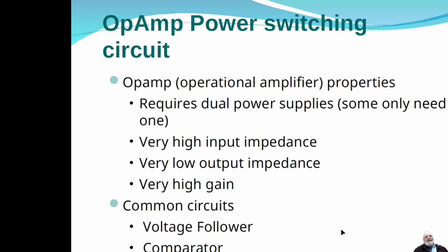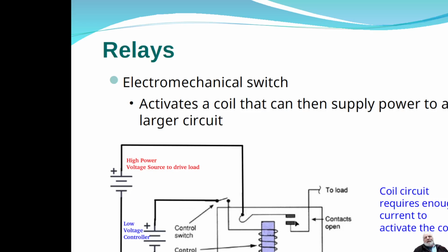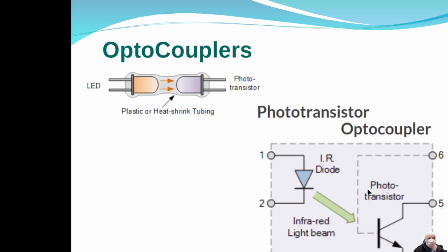Now, for the relay that we just talked about, you can apply AC to the load once you close these contacts. The relay itself depends on the design: some relays can be activated by AC, and some must be activated by DC. But whether the relay is activated by DC or AC, the load, through a relay, is just a physical switch through these contacts. It can be AC or DC to the load.